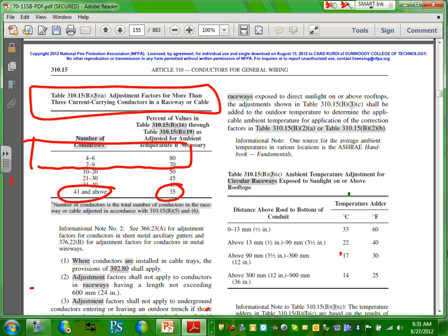Do you want a feeder to trip and take another feeder with it? So keep in mind, this is beautiful to look at, but typically that's what you're going to be using. You're going to be grouping up to 9 hots in one conduit. More than that, it becomes really tough to justify it. Okay, everybody knows how to use that one.